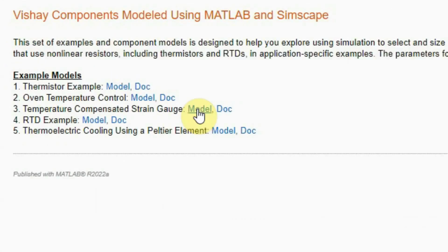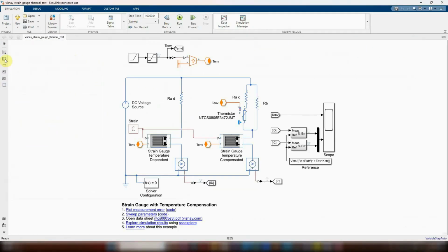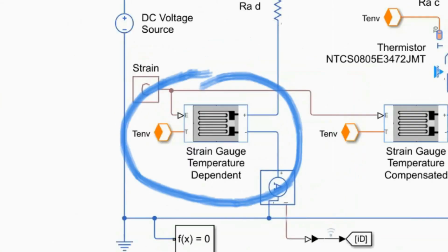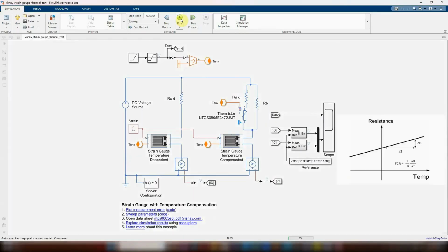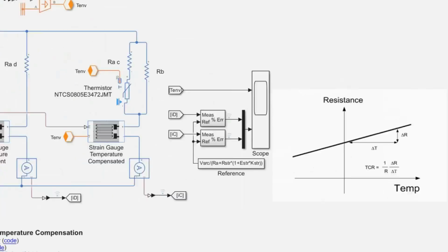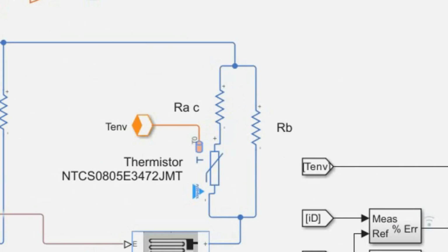We can now study another type of application for Vishay NTC thermistors. In this case, the temperature compensation of another sensor, for example, a strain gauge probe. A resistive strain gauge sensor has a positive temperature coefficient, which can limit the temperature range for its use. Placing a network of fixed resistors with a thermistor can help to reduce the global variation of resistance in function